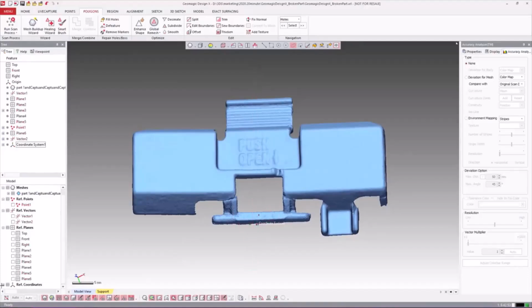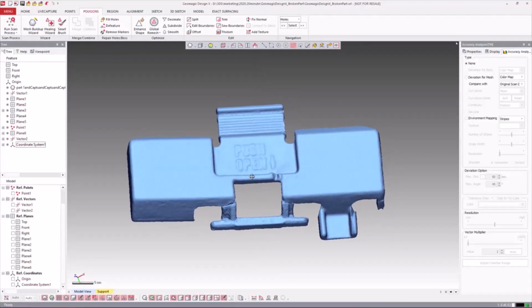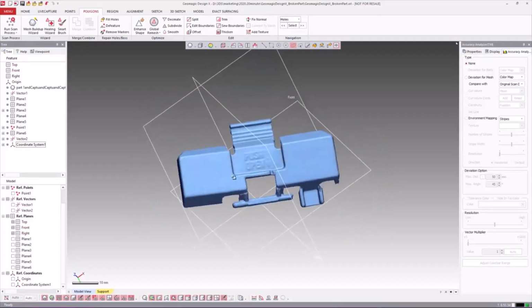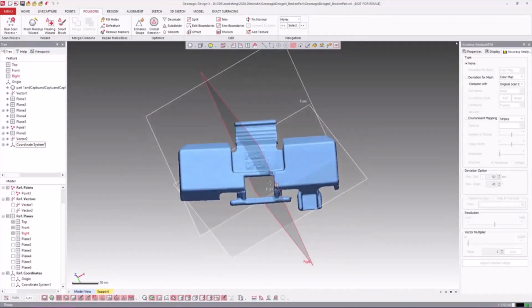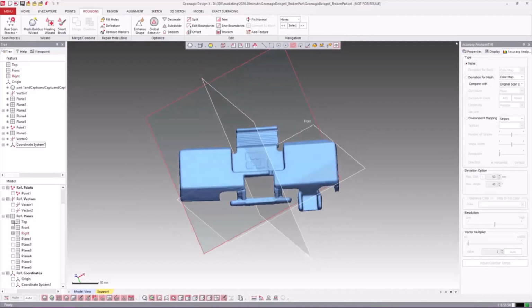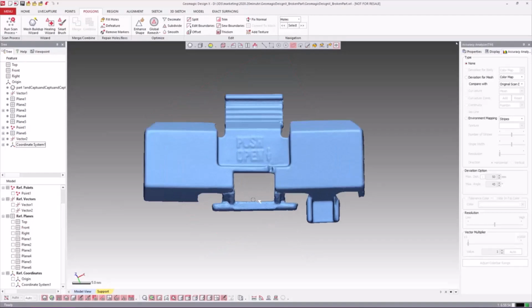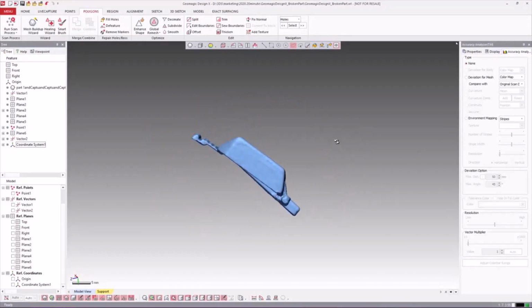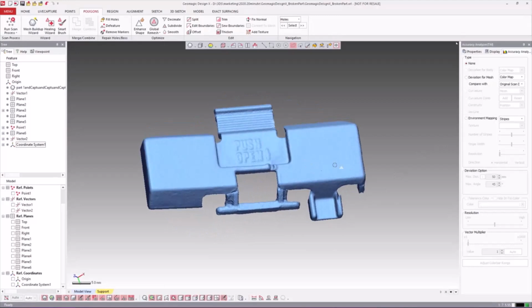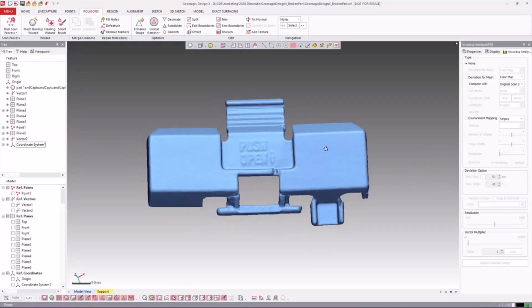I'm going to turn off my little reference coordinate system here, and let's put this thing on our real coordinate system now that we're lined up. So a part that this warped can be a little bit fun to do to get things to line up to where they want them. But since I lined this up pretty well with this side, and I'm saying the other side is kind of bent out, we're going to use all the data from this side to check this out.